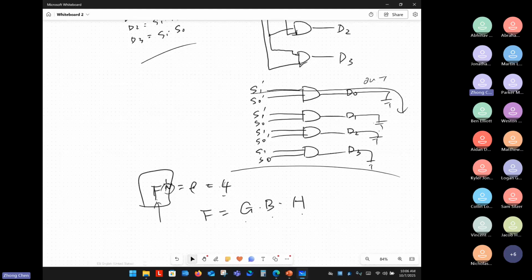So now you see the problem here. That's assuming the design here. So this is a NAND gate, actually a 2-input NAND gate. We should be able to calculate the G value, and you can add the inverter in there, and the G value will not be changed. So I can calculate the G.